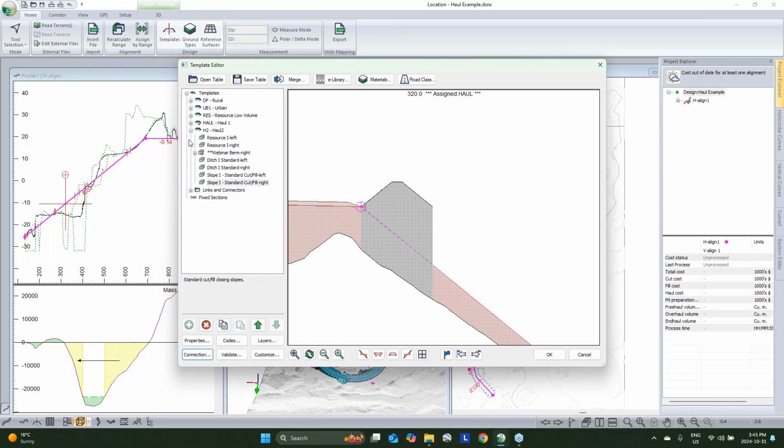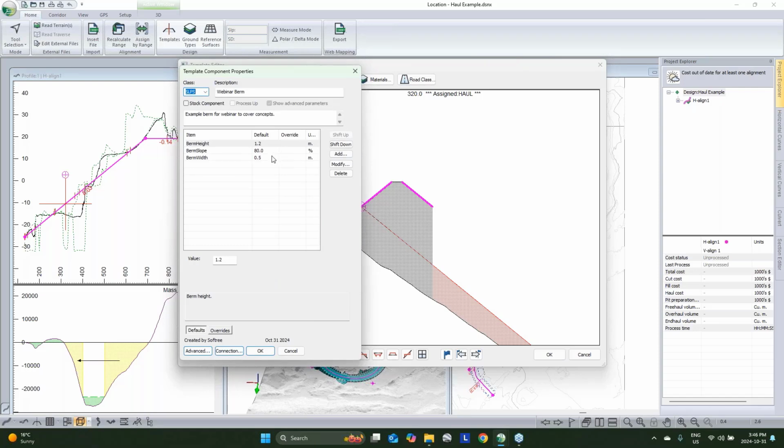So one way we could deal with it would be to just say, well, let's put a subgrade fragment that goes across the bottom, and we assign the variable. Great. For this one, instead of assigning a variable, if we change stuff, we don't want to have to calculate what that other length is ourselves. So we can include that as a parameter.